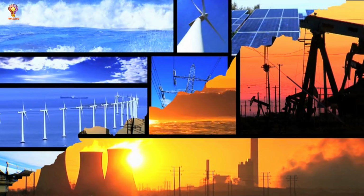3. Hydroelectric innovations. Hydropower is one of the oldest and most reliable energy sources, but new technologies are improving its sustainability. A. Pumped storage hydropower (PSH) acts as a giant battery, storing excess electricity by pumping water uphill and releasing it to generate power when needed. Improves grid reliability and integration with renewables. B. Floating hydropower. Uses floating turbines in reservoirs or oceans, minimizing land impact. Can be combined with floating solar panels for hybrid energy production.